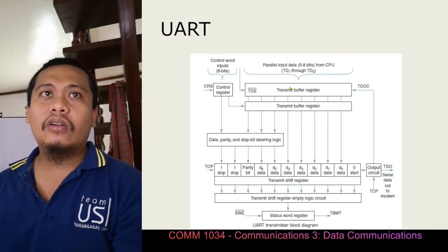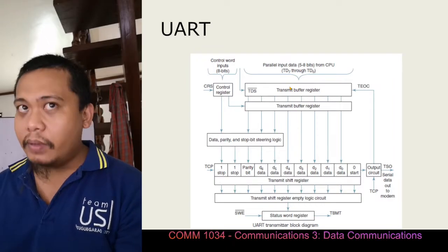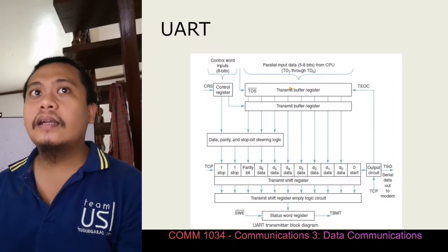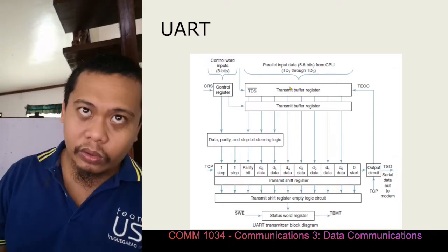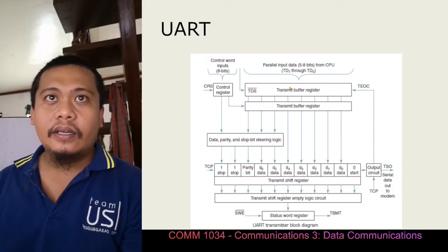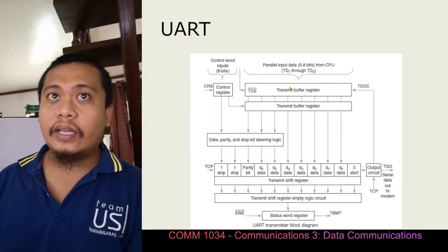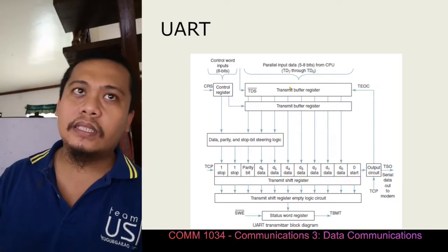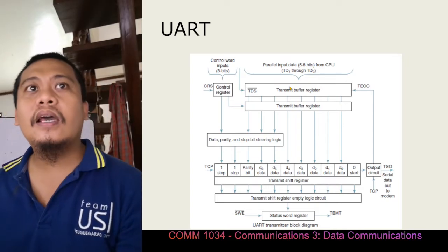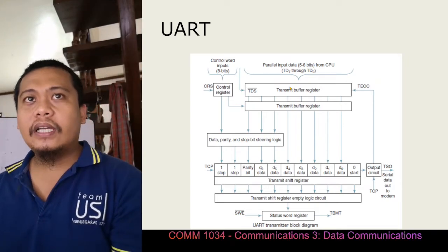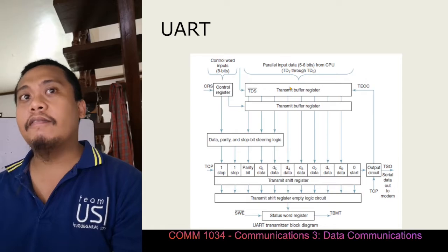The control word specifies the number of data bits per character, whether a parity bit is included with each character, and if so, whether it is odd or even parity, the number of stop bits inserted at the end of each character, and the receive clock frequency relative to the transmit clock frequency.